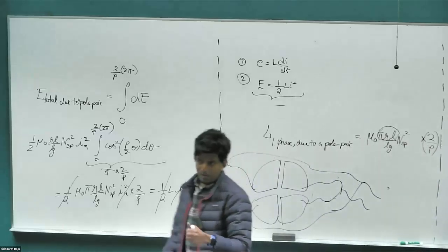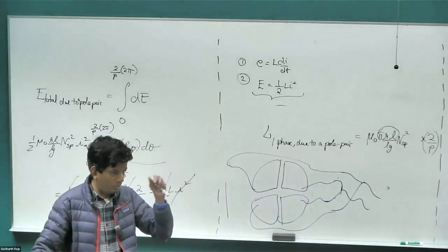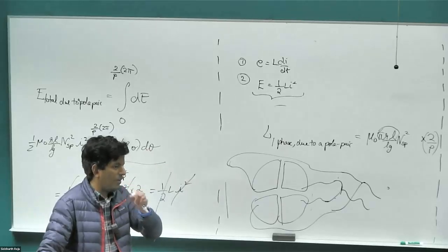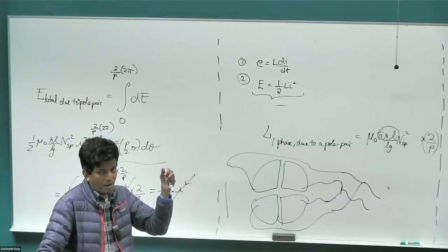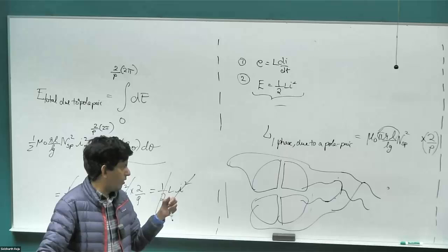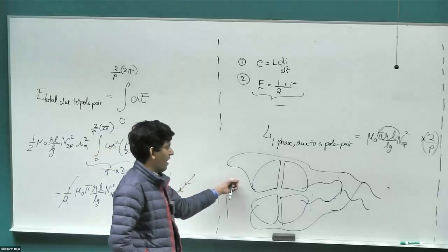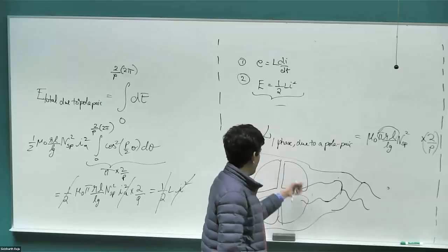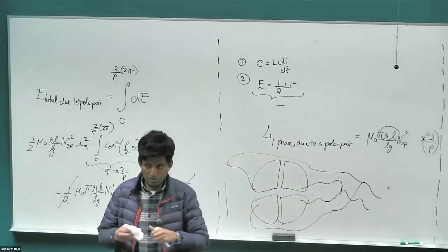When you have 6 poles, you have multiple options. You can have coils in sets of 2, with two coils in series and then 3 sets in parallel. Or you could have 3 coils in series and 2 sets in parallel, or you can have all of them in parallel, or all of them in series. As you go to more and more pole counts, you have more and more options for how you parallel them and combine them. If I were to tie all of these windings in series, what will be my net inductance?